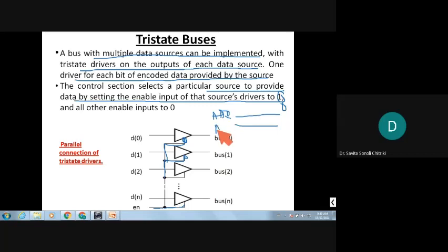That means 8-bit data bus as well as the address bus is there, right? So we had seen one control signal called address latch enable. So only when the ALE goes high, whatever data is there on this bus is treated as address.